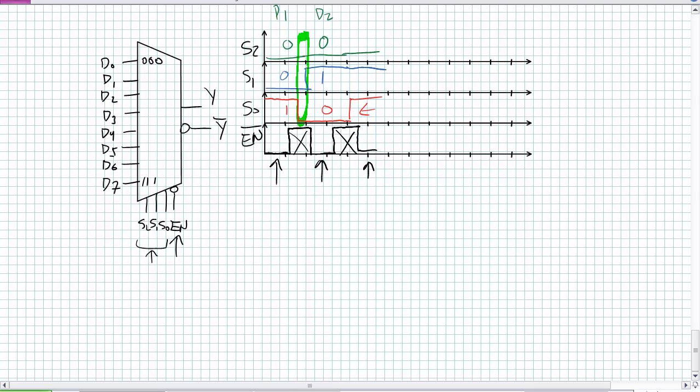It's called strobing. Think about a strobe light. Someone moving around in a strobe light looks like they're suddenly transitioning from position to position. That's all I'm doing. I'm strobing it. Active low, take that input now. They're still trying to shuffle their seats, just ignore it. Okay, they're in their seats, take that. They're shuffling around, ignore it. Okay, they're in their seats, go ahead and take that data. So that's a pretty cool application of the enable.